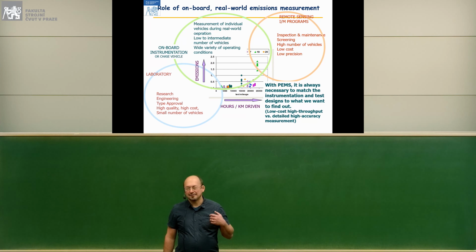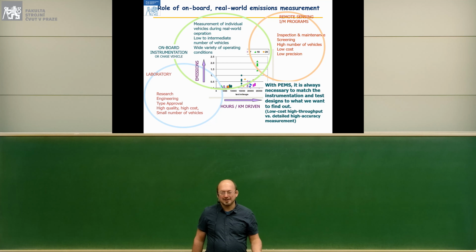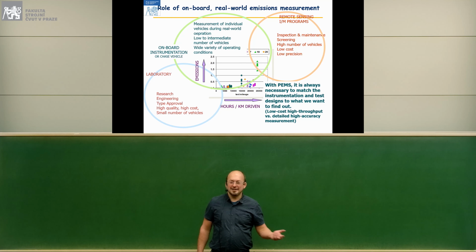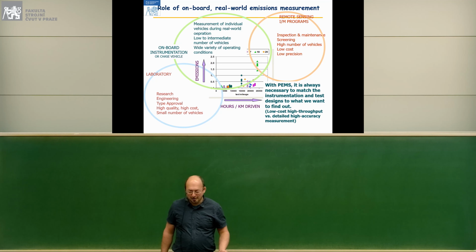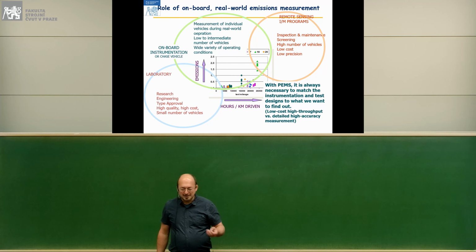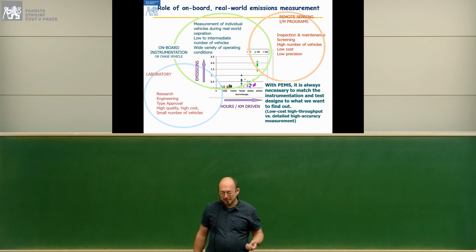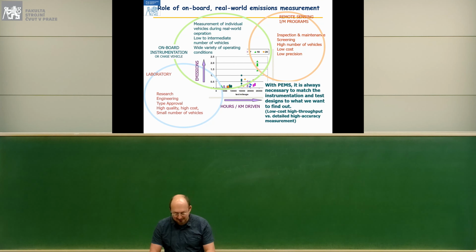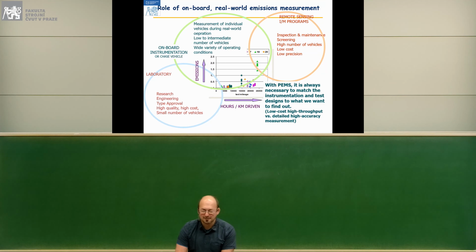Then we have so-called aftermarket issues like tampering with the engines, tuning them to higher horsepower, removing particle filters, or at least not maintaining the engines properly. If you don't maintain the engine, well, there might be some problems. And particle emissions are one of the best diagnoses of the combustion process of the engine. Many problems with the combustion process or with the engine you see on emissions, especially particle emissions, way before you see them on drivability or fuel consumption.